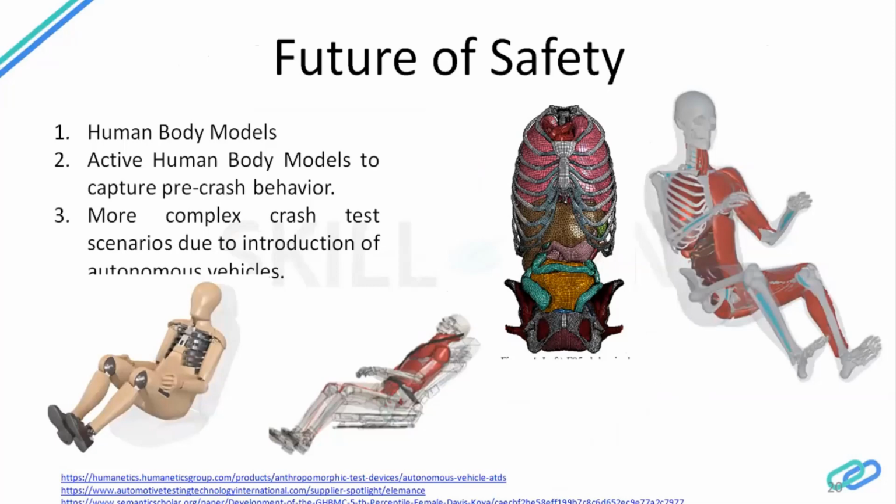So instead of using the FE models of these hardwares, what you can do is take a human being, put them in an MRI machine, take all the images, create all the CADs, mesh them, and you can have an actual human skeleton like this. You can see here, like this one. This is the CAD model, and this is the FE model of the same CAD, so you can use this, right? So these are called human body models.